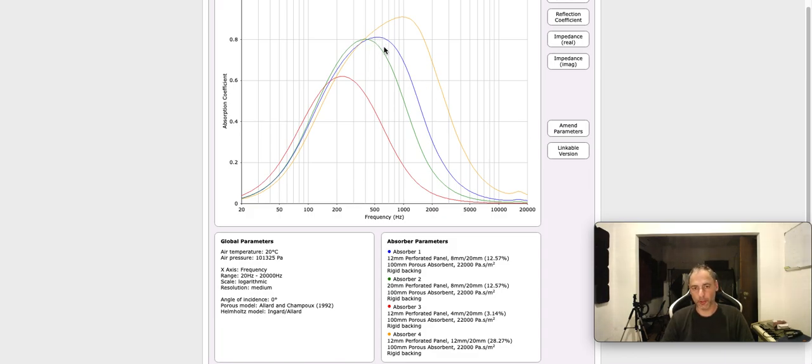So this is also important because, especially if we're dealing with large room acoustics and large spaces, most of the absorption at high frequencies is made with the air enclosed in a room. So we might want a panel that is actually more narrow in terms of the frequencies that we are aiming for.